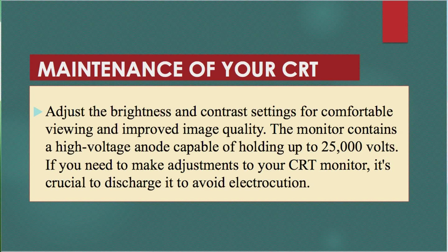The monitor contains a high voltage anode capable of holding up to 25,000 volts. If you need to make adjustments to your CRT monitor, it's crucial to discharge it to avoid any problems.